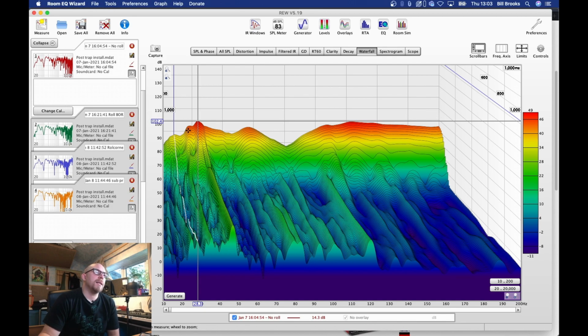This is a case in point of why you can't just look at a momentary frequency response of the speaker system and expect to ascertain where the frequencies that are sustaining and ringing in your room are. You would imagine there's no problem there. In fact, the only problem is that there's not enough of that frequency band. But when you listen in the room, because of the sustained aspect of that frequency, you'll find that there's actually a build up there. So your instantaneous frequency response is not telling you the whole story.